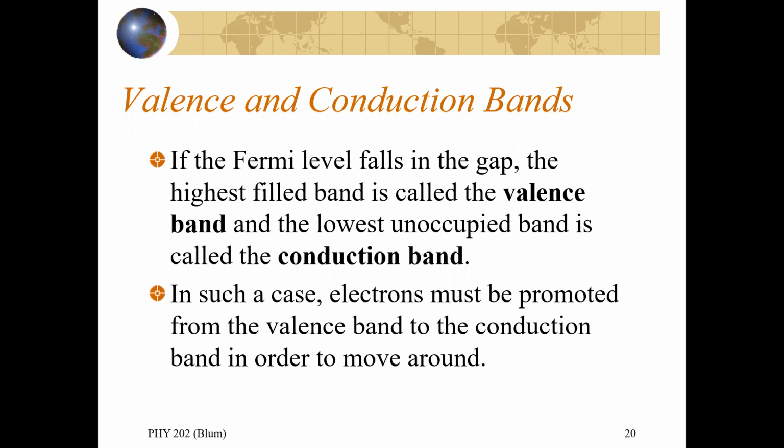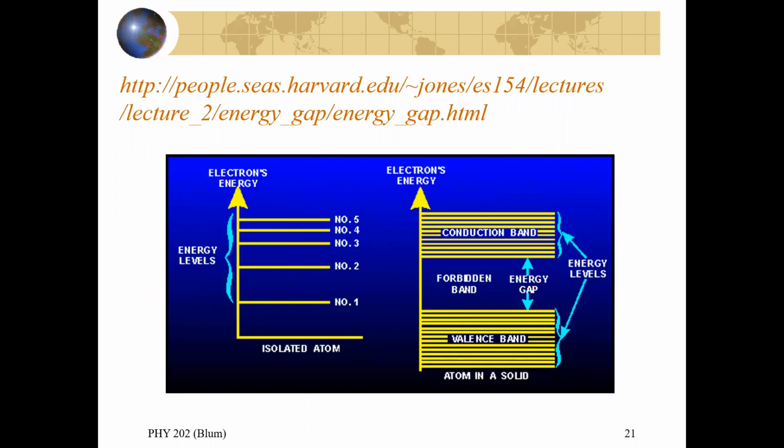So again, we're semiconductors, so our Fermi level came up to fill up a band, and we're at a gap. So we're talking about a gap between 2 bands. The full band below the Fermi level is the valence band. The empty band above us is the conduction band. Valence full below, conduction empty above. So our Fermi level was in this picture here at the gap.